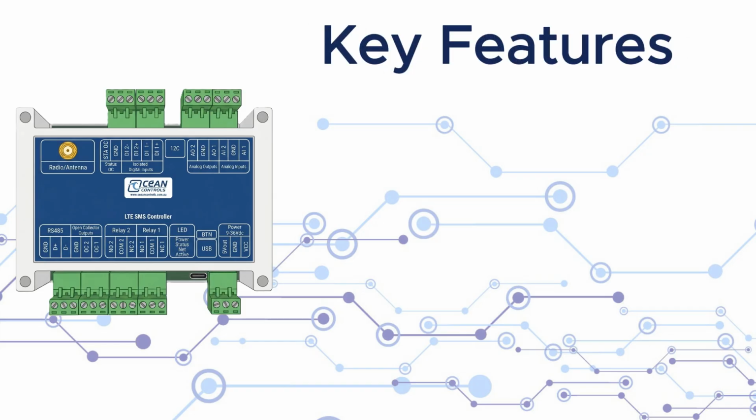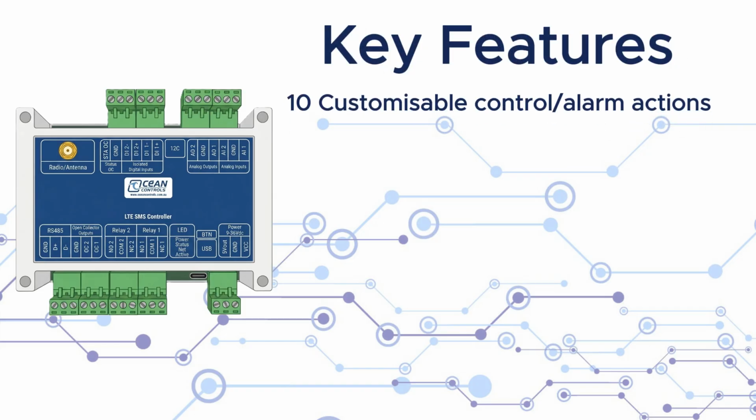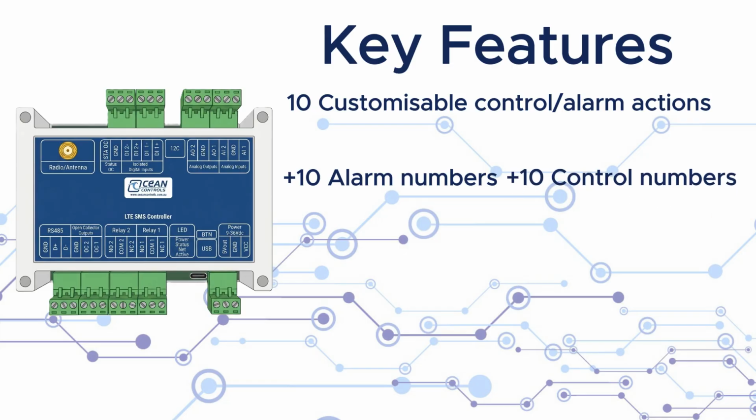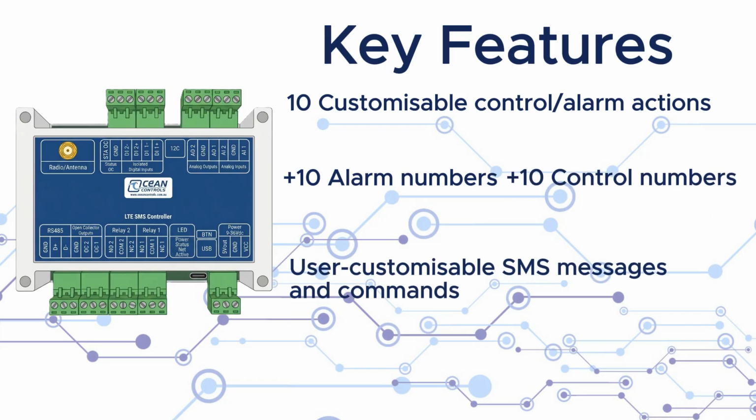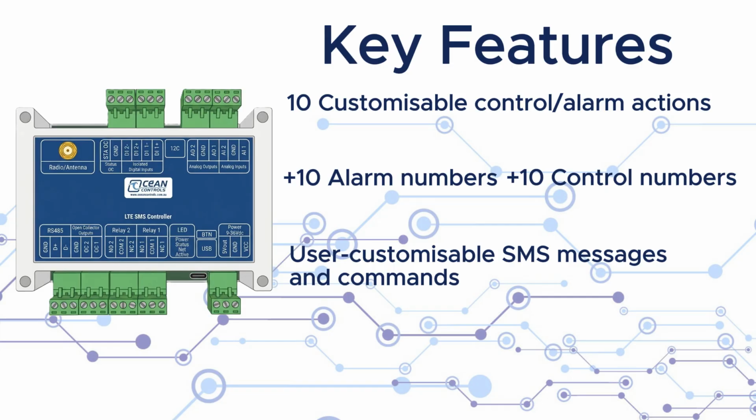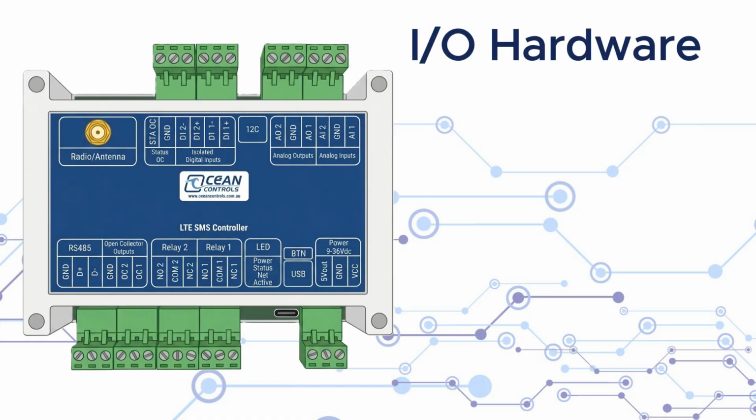The key features of the unit include up to 10 user-defined controls, including both alarms and actions, up to 10 phone numbers for alarms and an extra 10 phone numbers for control, full support for custom SMS messages for both control and alarm notifications. On the hardware side, it's equipped with 2 analog inputs and 2 analog outputs.